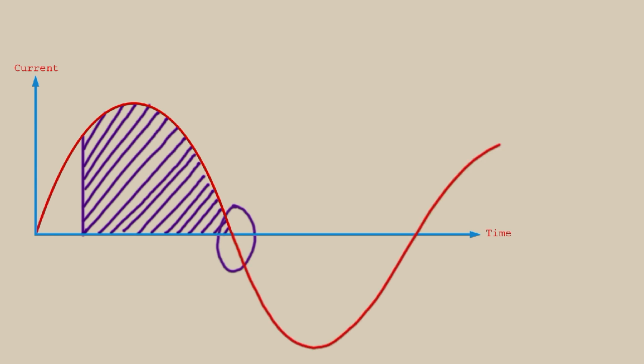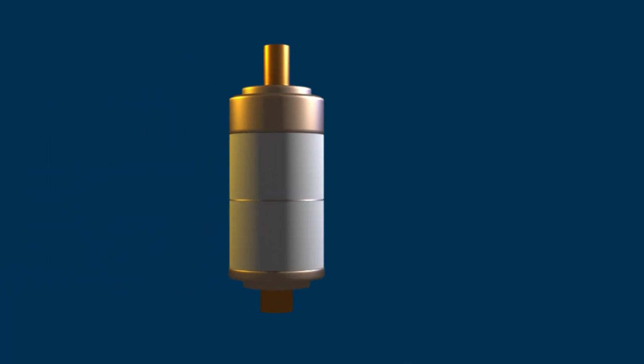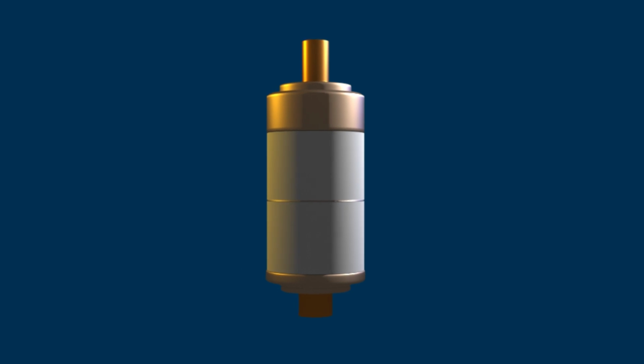Okay, let us come back to the actual topic. A vacuum interrupter, or VI, is a vacuum chamber within the vacuum circuit breaker where all of this happens during the operation of the CB. The image on the screen shows the VI. It is actually a removable part of the VCB. It is to be fitted into the CB mechanism. Being a replaceable part, it can be swapped with a new one when needed.